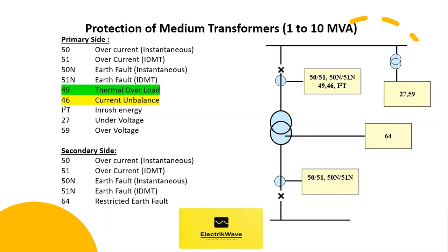If the load is around 135%, the overcurrent relay will not protect, but the transformer will get hot and lose its life. Thermal overload protection will help in this case. It is also beneficial to monitor the overload conditions in the winding and the core separately.